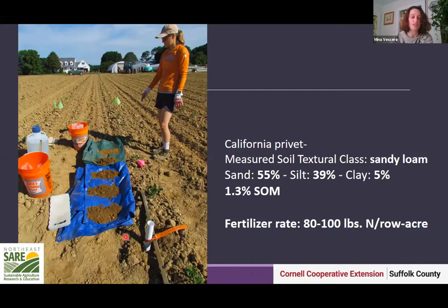So our initial installation of these lysimeters was set at 25 inches and that porous cup was at about 18 inches. I don't think we collected maybe 3 leachate samples from these lysimeters. So we installed much more shallow ones this year so we could actually collect some of that soil water and be able to analyze it for total nitrogen.